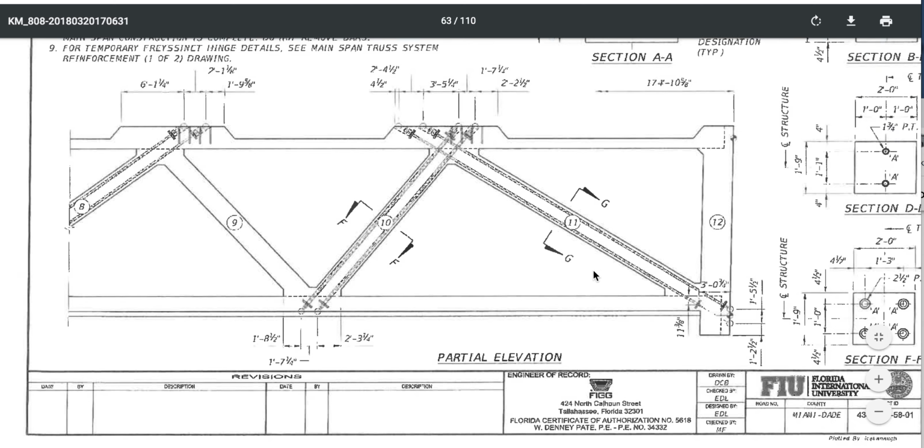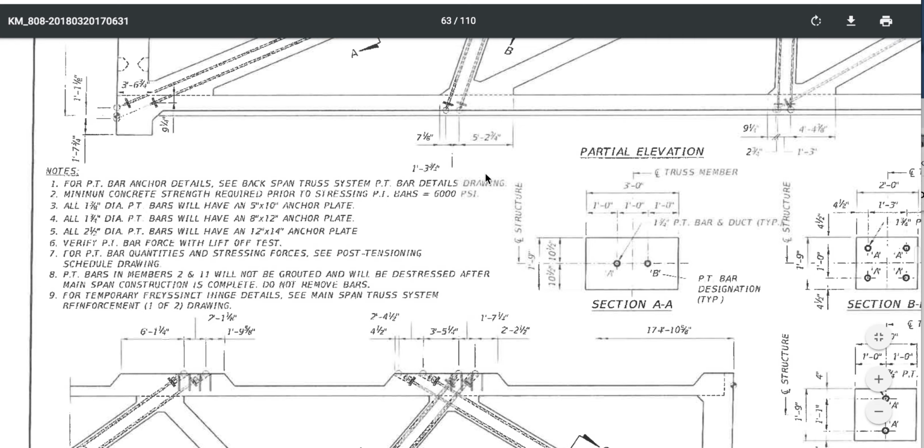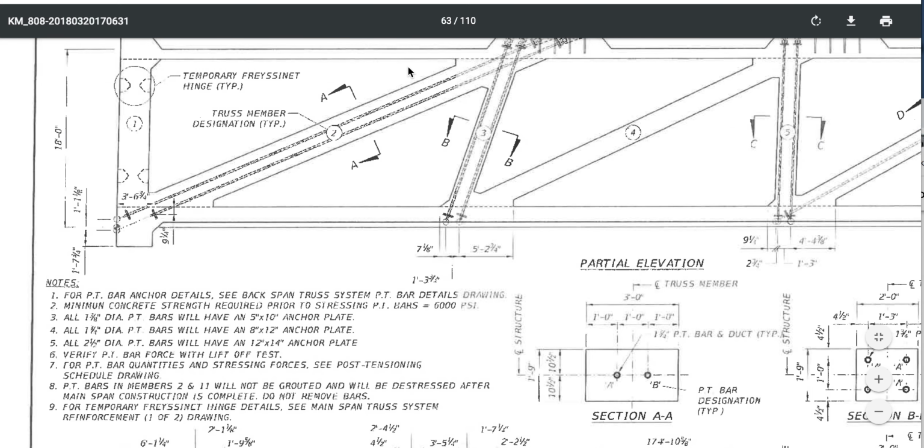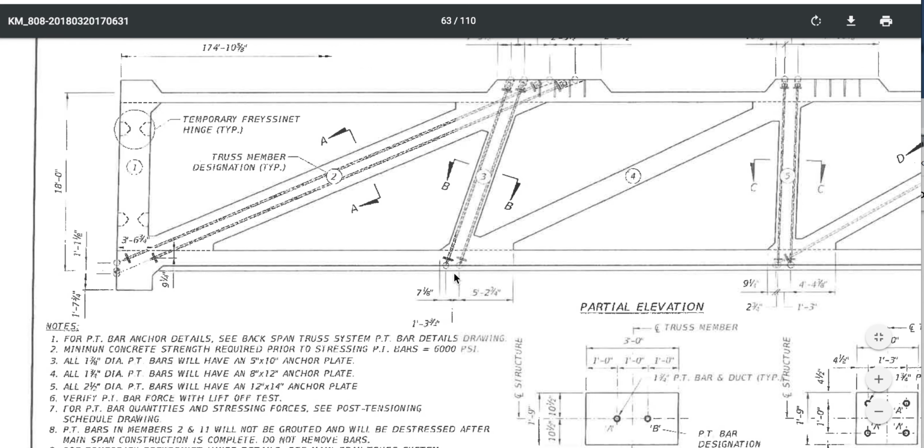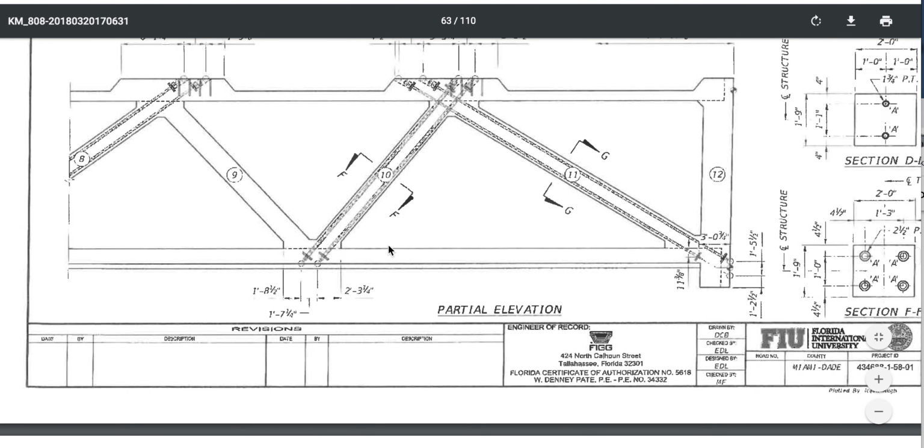The sagging of the deck, caused by the tied arch, caused a reaction of this pushing down from here. So the hinge point would have been from this point here, number 3 and number 10, creating this new triangle that lifted up. After they detensioned, this allowed it to dip down even further and to crack like hell. As I told you, if they would have run a new line across there, they would have seen a significant amount more sagging.